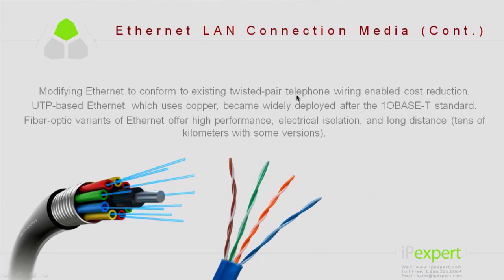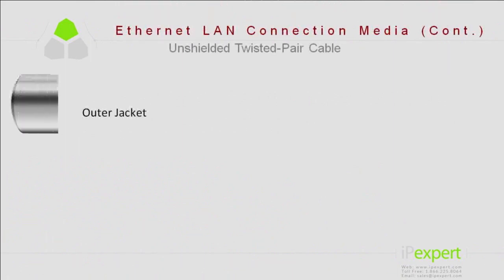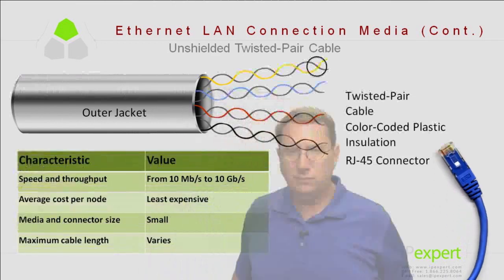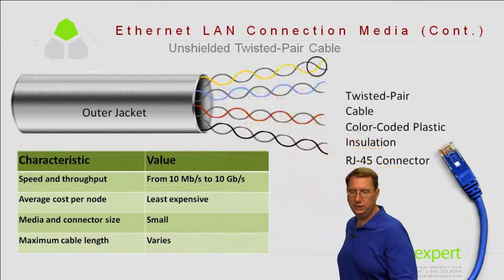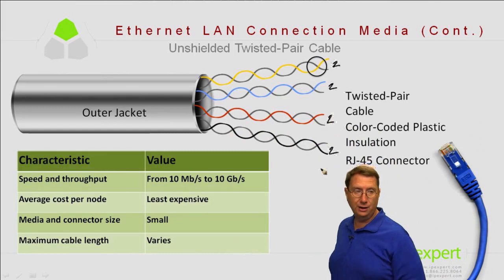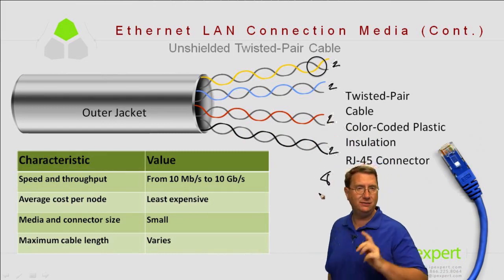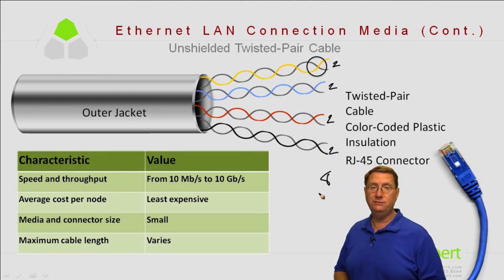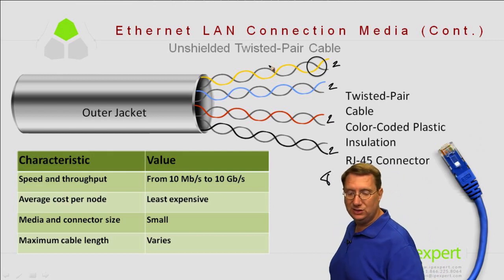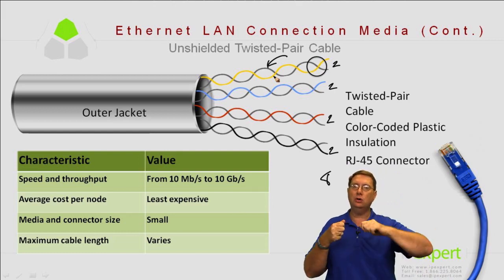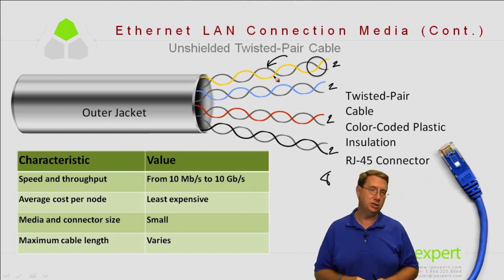All right, with that being said, let's move on in our presentation. Now, like I said, we would talk about this idea of shielded and unshielded twisted pair. According to the illustration, let me grab a pen. Notice we have 2 wires, 2 wires, 2 wires, 2 wires, adding up to a total of 8 individual conductors, but each of those conductors is grouped in pairs of 2. Now, we have this idea of twisting. I'm going to take a pair, 2 individual wires, and turn those, and it's going to be something like 22 rotations per inch.